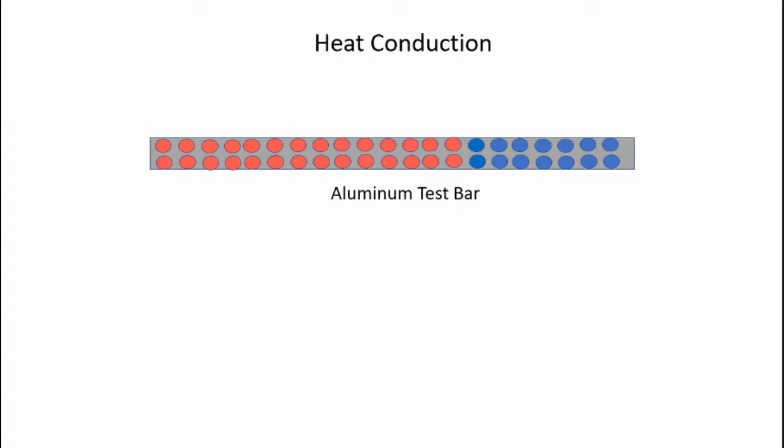And so heat will continue to move towards the right on the bar, as depicted by my pink circles. But overall, the temperature of the bar on the left decreases due to cooling effects. The heat continues to move to the right until the temperature becomes cool enough that heat flow no longer exists. And eventually, the bar will equilibrate to the ambient air temperature around it.